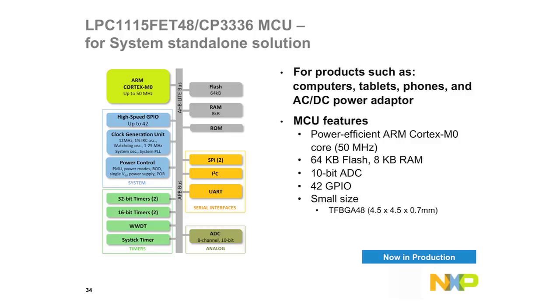There's 42 GPIOs, so there's plenty of GPIOs for controls of the load switches, data muxes, whatnot, and maybe even throw in another PTN to make a dual port design. And it comes in a small BGA package.